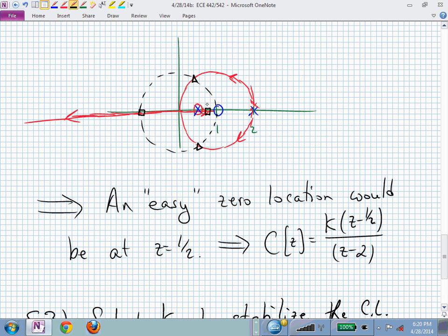And you can see that those squares are not moving at the same distance, because it takes k from a large value up to infinity to get it to z equal 1, and it takes k up to a large value all the way to minus infinity to get at that infinite distance. So now we have a unit distance versus an infinite distance being traversed for the same range of gain k.